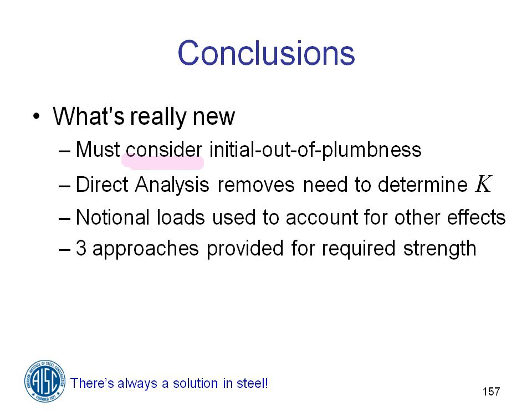And the bottom line is we have 3 methods that we can use. We can use the effective length method that we've been using all along. We can use the direct analysis method, or we can use the first order analysis method.